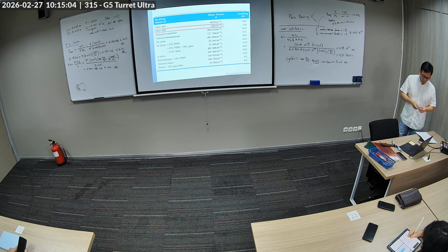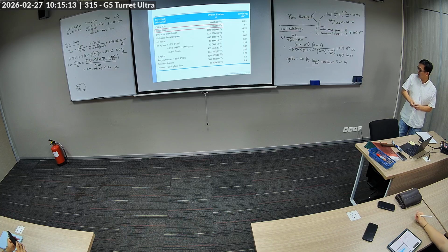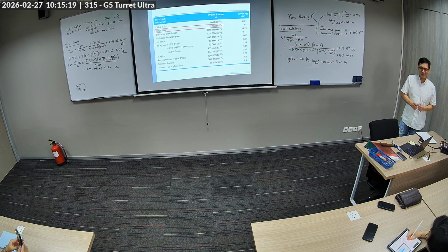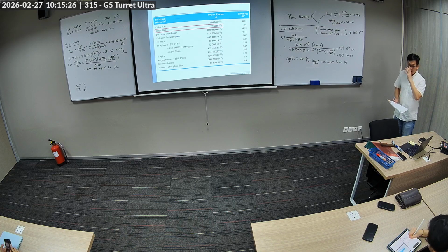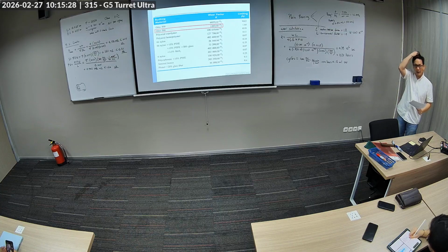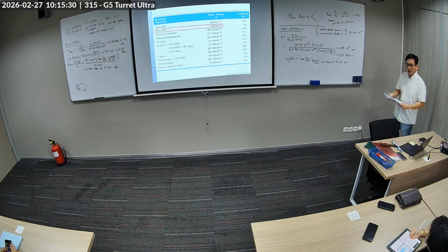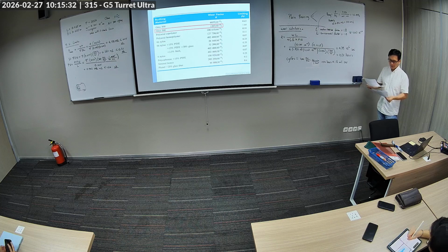Questions on this problem? Will it fail at like 1 minute after 1,331 hours? No, it's an estimate. Again, the limit here is the wear. Will it still work? Yeah, it'll still work, but you're wearing out the bushing beyond its wear limits. So be careful. Okay?